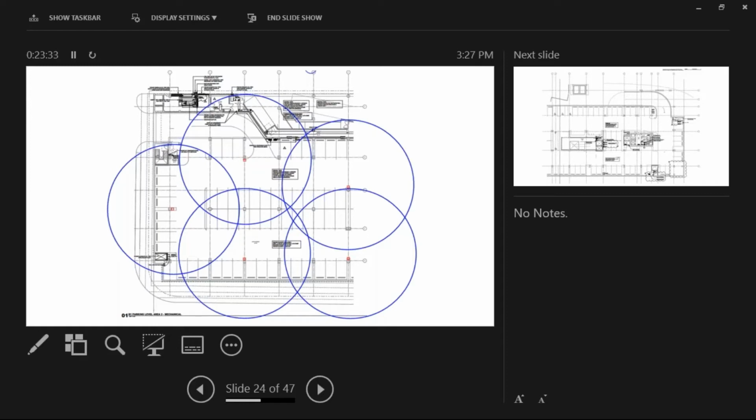And yes, you can make use of the perimeter walls by not spacing your sensors that far apart, such that as the ambient air within that envelope diffuses and convects, there are more sensors to pick up on it. So you're kind of compensating for the area where you can't get sensors into. You're trying to take advantage of the natural diffusion and convection that takes place within the ambient atmosphere in that envelope.